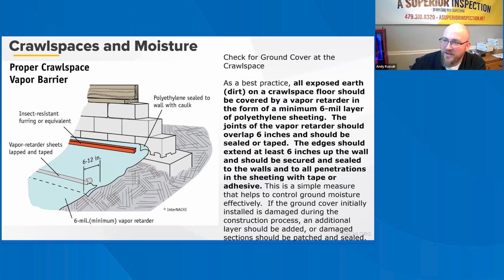Non-vented crawl spaces are also recognized as suitable, especially in hot, humid climates where outdoor air adds moisture. This method involves several factors: functional exterior grading and site drainage, minimizing air leakage between outdoors and crawl space, insulation on the perimeter walls, such as rigid foam, and the use of 6 mil polyethylene ground cover, damp proofing of the foundation walls, and some ventilation with conditioned air. Recent model building codes require a non-vented crawl space to be supplied with conditioned air and a return air transfer grill or mechanically ventilated. Inspectors should check local codes when inspecting these crawl spaces.